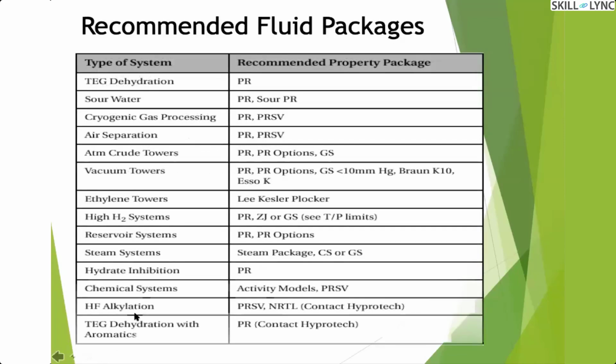And then next, the important thing that you have to look at in the flow is here. You have to select the appropriate fluid package for your use, because the fluid package is important while using the simulation. When you select a wrong fluid package, each of that fluid